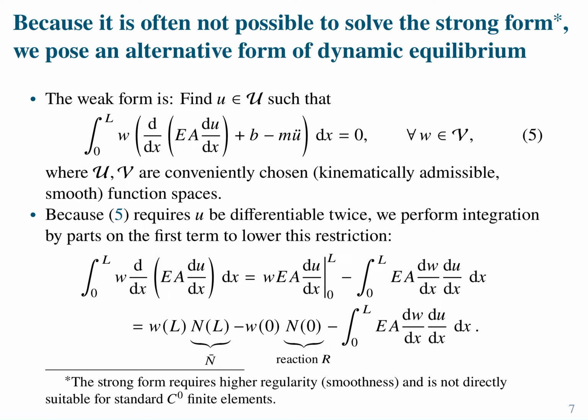So in essence, just simply by applying integration by parts, you get this term, right? Where when you replace by what it is, because it's the actual force at L, in our case, remember that we're calling that N bar, right? It's the value that we're prescribing of the force. And then on the left, we have the reaction. But as a bonus, we have this term, and you can see that it has balanced the derivatives. We always want to do that.